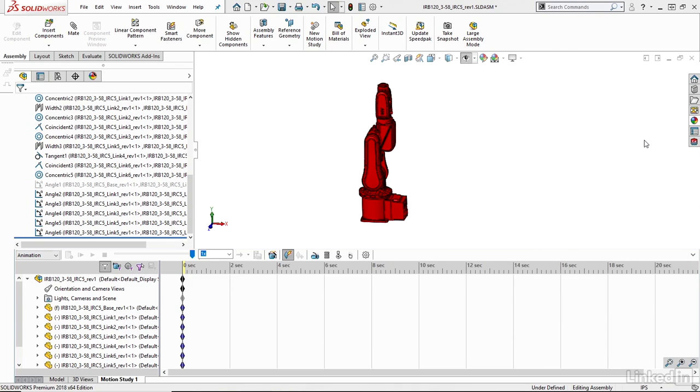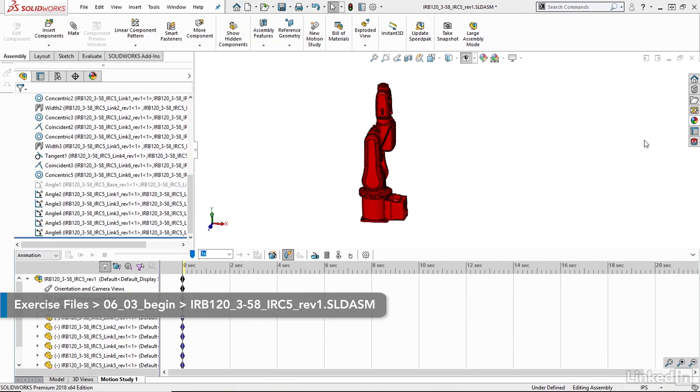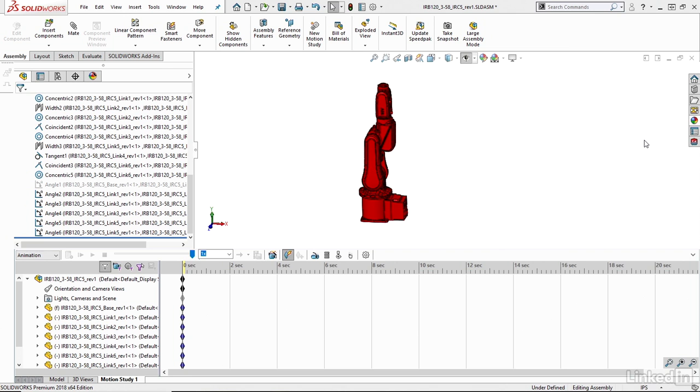Using motors is another method to generate precise and more complex animations. When adding motors, I have even further control and options to my possible motions, and this can help replicate the motion with an even more realistic approach. So to add a motor, I can just take a look in my motion manager here, and this icon here is adding a motor.